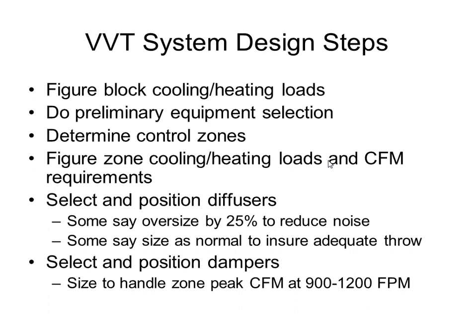Obviously, it doesn't always work that way. A lot of times you just get a model number of an existing unit and you just say, hey, I need 15 tons because that unit was 15 tons, but that is not the right way to do it. A lot of things were oversized previously. We always want to do the heating and cooling loads before we actually select equipment.